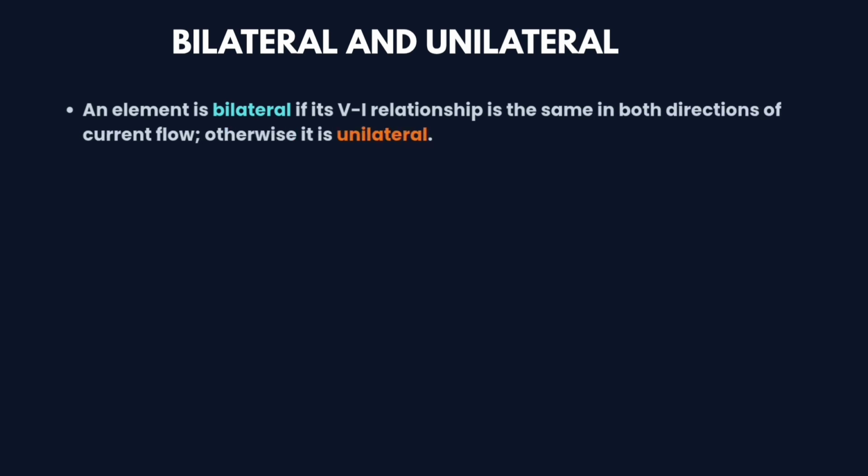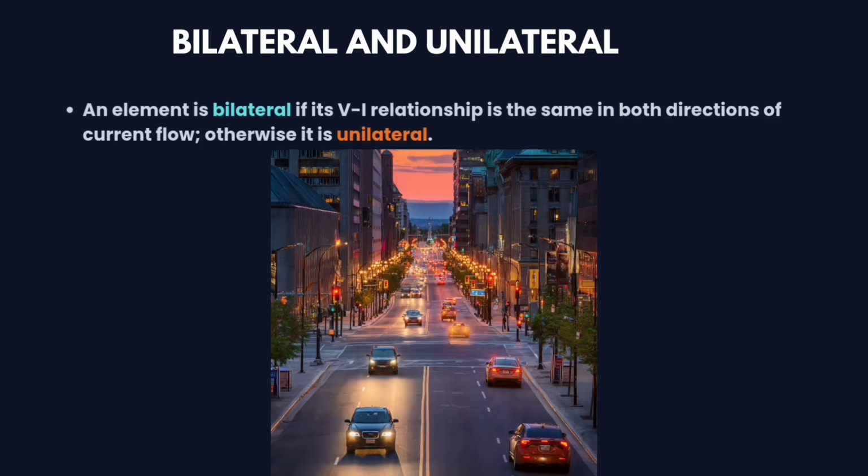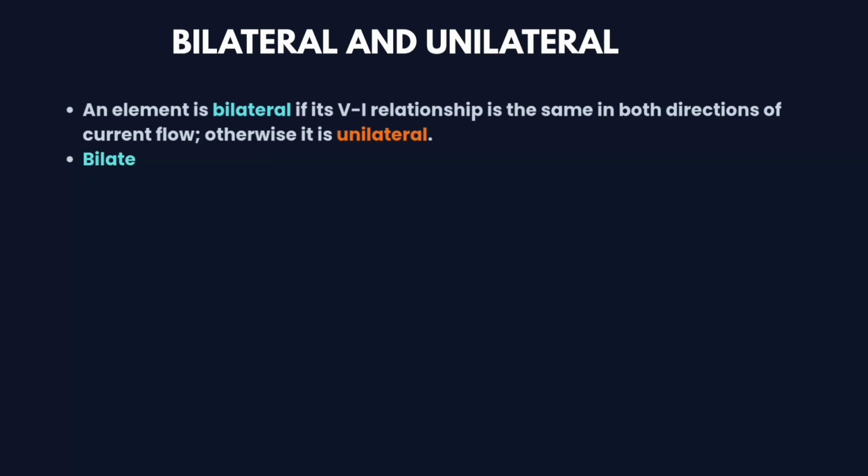Bilateral and unilateral elements. A bilateral element behaves the same even if the direction of current is reversed. In other words, its voltage current relationship remains the same in both directions of current flow. Think of a two-way road where movement is allowed in both directions. Resistors, inductors, and capacitors behave similarly, so they are bilateral elements.